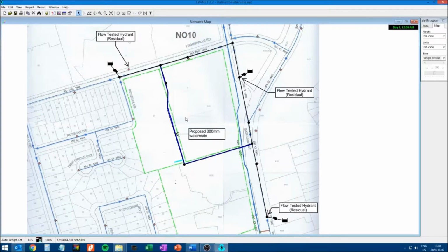based on some background calculations, we have calculated that the maximum fire flow based on the Fire Underwriters Survey formula for the proposed development will be about 11,016 liters per minute, which is 183.6 liters per second.